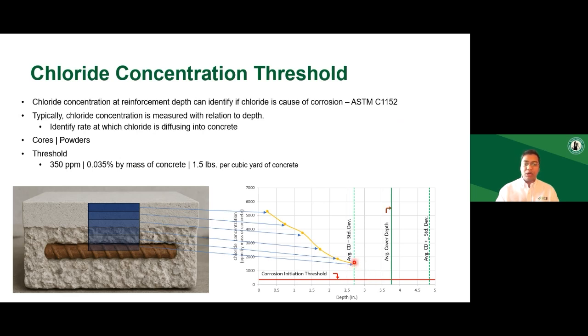If this last point were to be below this line, then the way I would read it is that currently there is no risk for chloride-induced corrosion, as of now, but it might be a risk in future. So you need to be on the lookout for the chloride measurements at the rebar depth.